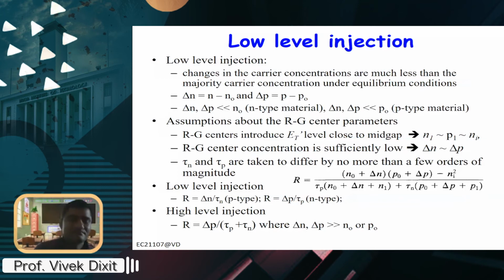Okay, sir. Sir, do they trap only impurity ions or something else? Okay, it depends on individual kinetics, but it is found that these phosphorus atoms tend to take away the impurities, because in silicon most of the time gold is the dominant impurity. They can take down other impurities also, but it depends on the individual reaction kinetics. Okay, sir.